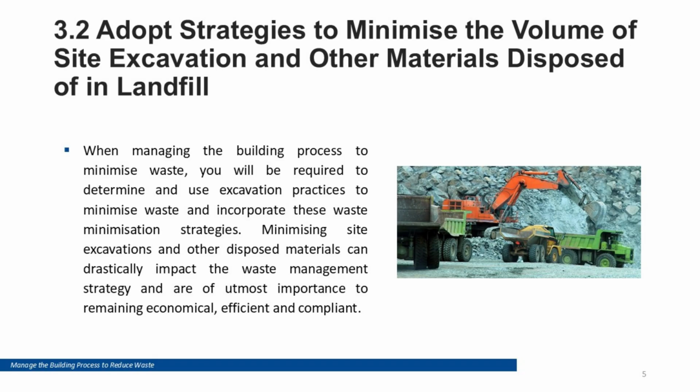Excavation spoil and heavy materials can quickly become a major disposal cost. Strategies to reduce landfill include accurate cut and fill planning, reuse of suitable spoil on site, and identifying lawful off-site reuse options where appropriate. Prioritize reuse pathways early, so material can be handled correctly and kept clean. Where reuse is not possible, ensure correct classification and transport to approved facilities to avoid contamination and compliance issues.